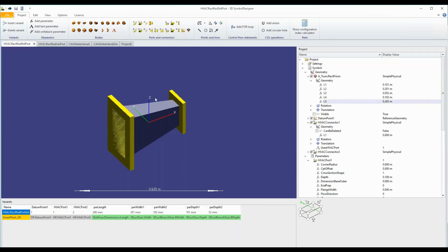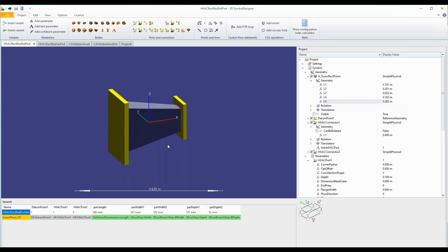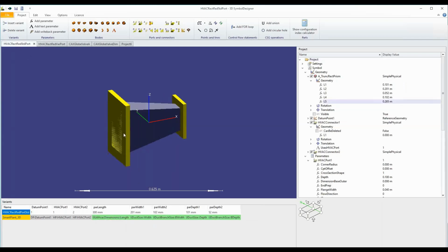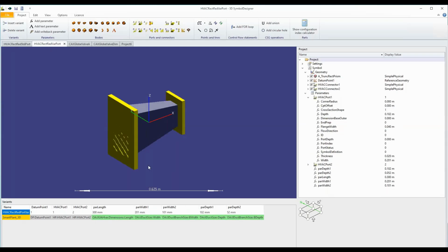This means when you place this one on the HVAC in Smart 3D, all these sizes are defined by the profiles that are defined in the catalog. In the other example, we see that down here we have occurrence attributes on all these parameters, compared to the other one where we don't have the occurrence attributes. For this example, we can reuse the settings for the depth, width, and so on, also in the parameters. More about this in a second.